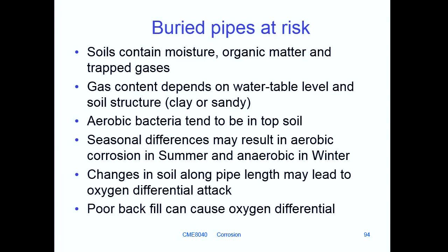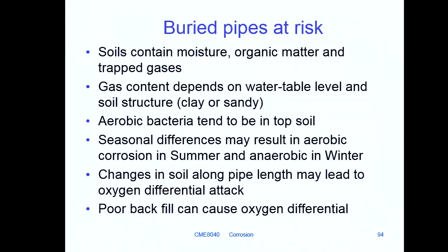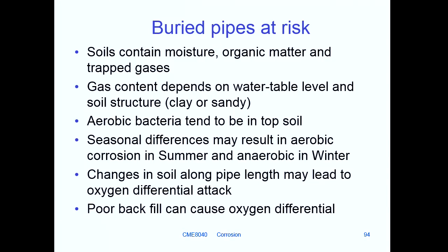And the trouble is, people sometimes get a bit carried away and they just dig a hole, pile everything up and put it back in again without thinking about the order of it. So you end up with a situation where your soil then has lumps of clay and then sandy bits, and then another lump of clay and sandy bits. And so poor backfill can then end up giving you oxygen differential along the pipe. So I've got a couple of images related to that.